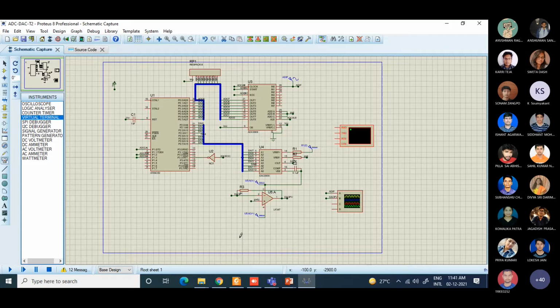We can do it using that, but T2 will be used. So that is one disadvantage, that T2 will be busy for that purpose. But otherwise, if your project becomes big and T2 is necessary, then you can have a separate clock source for ADC and then T2 can be released.